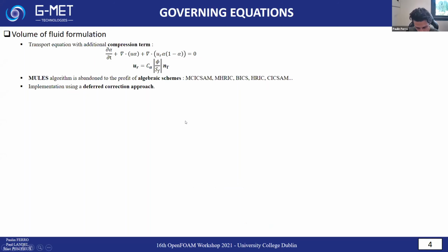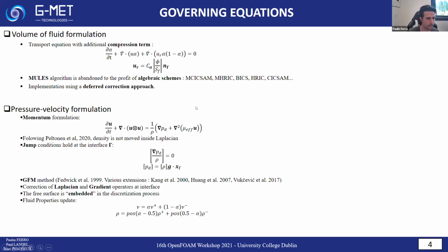So for the marineFoam governing equations, we start with a volume of fluid formulation, and we add the compression term as in interFoam. We abandon the MULES algorithm in favor of algebraic schemes. So we implemented modified HRIC, modified Ashwick, and so on. And this is very important: we did that in a deferred correction approach to have perfect stability.